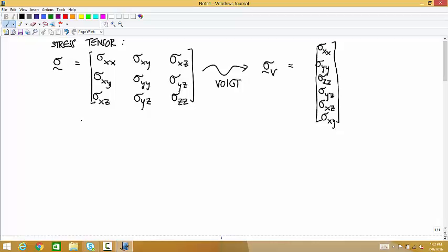And we can define the state of strain. We only do that in the Voigt form. There's no mathematical benefit for us to writing it in a tensor in a matrix form. We're going to use this matrix form for the stress tensor. That's why we're going to use these two different forms. These will both be useful at different times. But the strain we're just always going to represent as normal strains, XX, YY, ZZ, and then the shear strains in that funny order, YZ, XZ, XY.